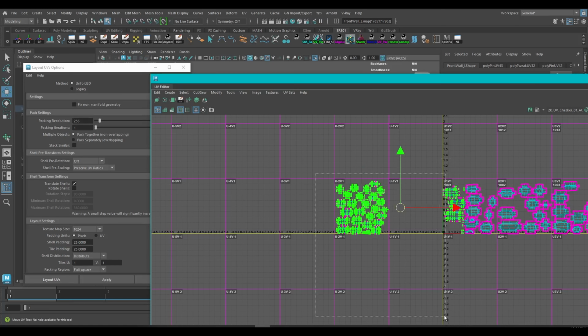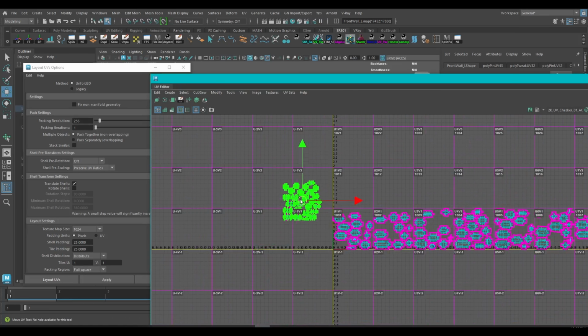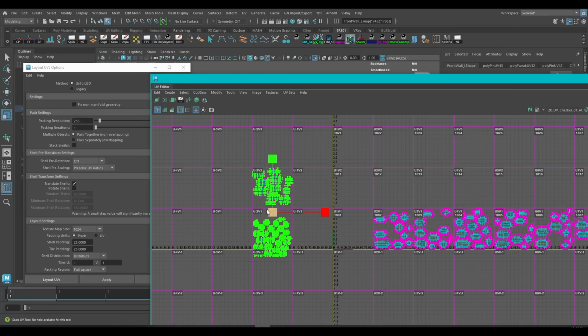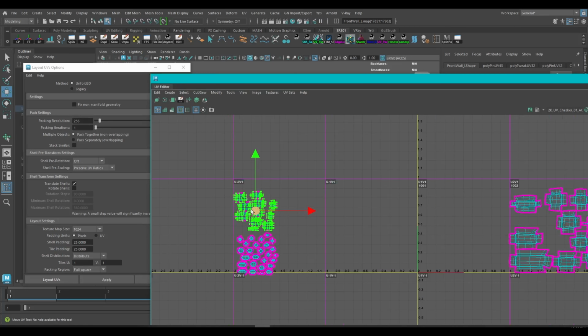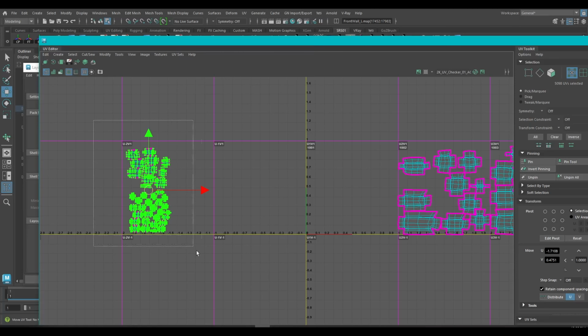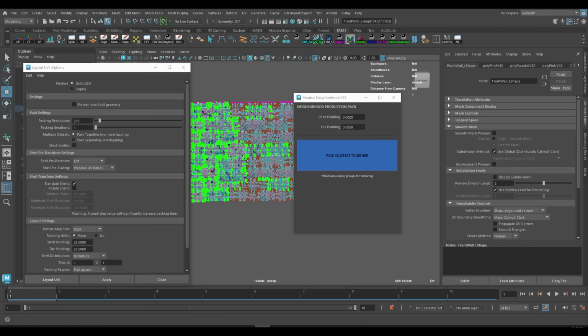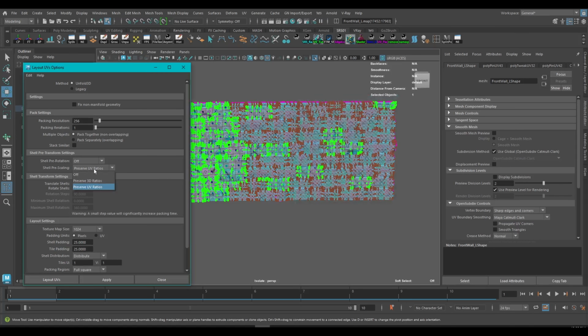It will always be packed together. When you lay out again, this packing stays. For example, if you pack these two together in one shell, it will scale down and keep it in the same shell. This option they should have given by default, but I don't know why they didn't. I created it for Maya 2022, 2024. It's not working for the 2024.2 version. So this is one method. This ratio has to be UV ratio, not 3D ratio.